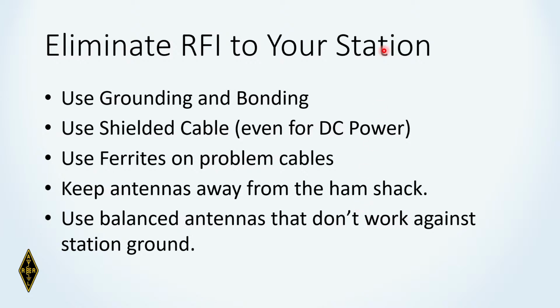You can use grounding and bonding techniques, keeping the ground connections on the back of the radios connected together. You can use shielded cable even for DC power. We'll talk about ferrites here in a little bit. They can give you solutions to problem cables.